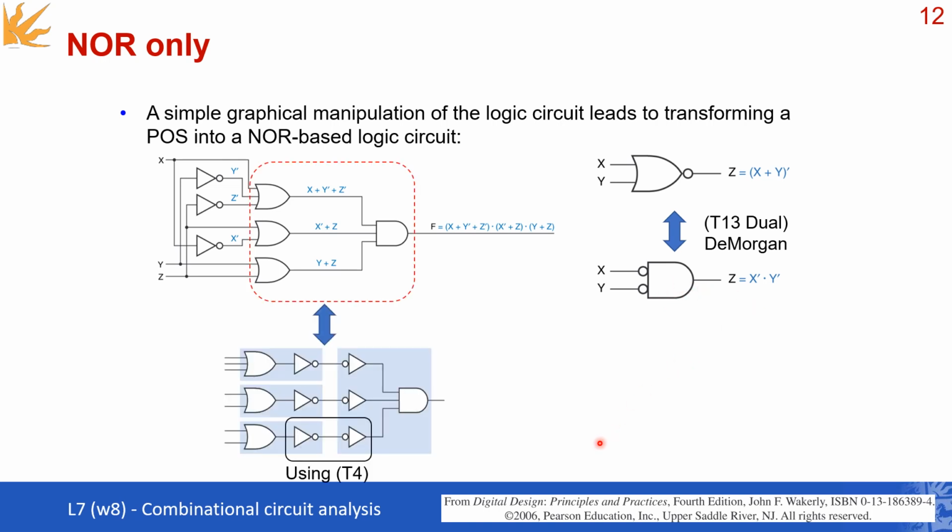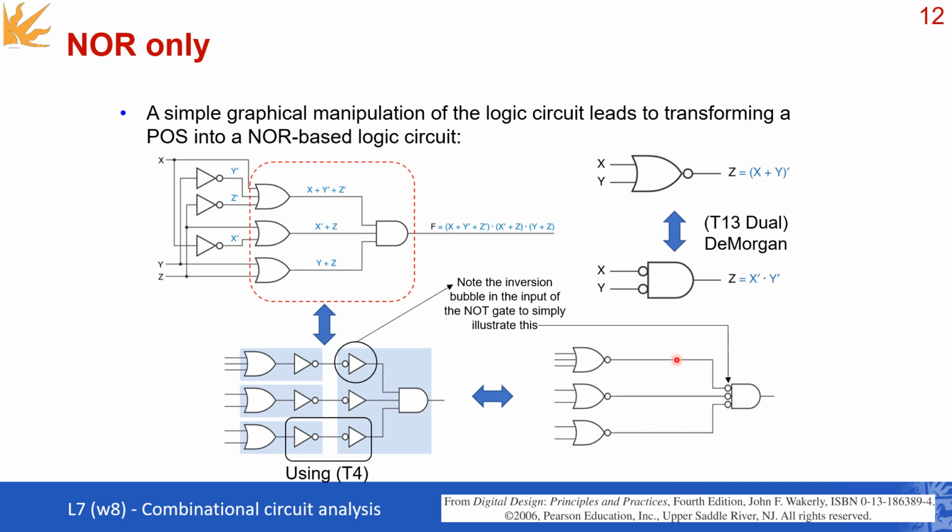And just like we did previously for proving the NAND gates, we're going to take advantage of involution. And therefore we achieve to have on the first level OR gates negated at the end, so this is an OR, and an AND gate with inputs which are negated, which is essentially, as we know from De Morgan, again an OR. And that's the proof that you can convert everything to a circuit that includes only NOR gates. And with that, we reach the end of this video.